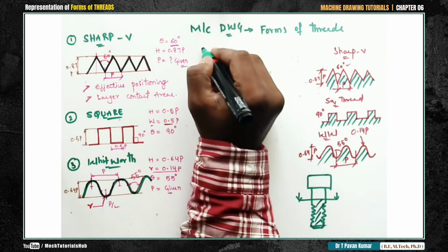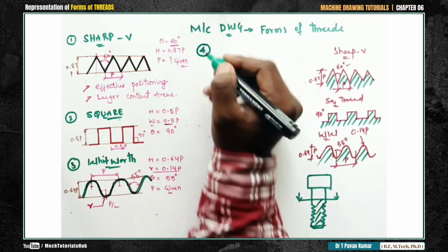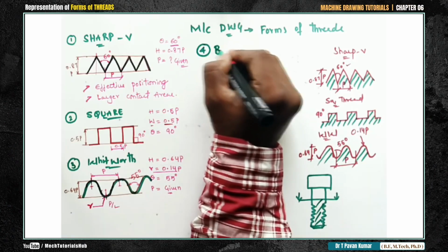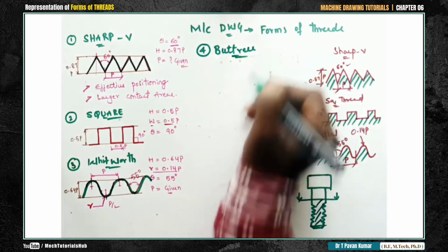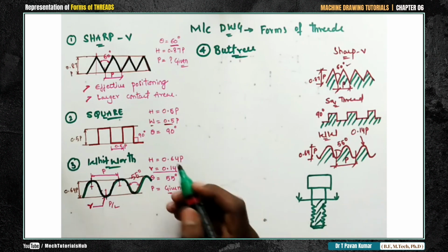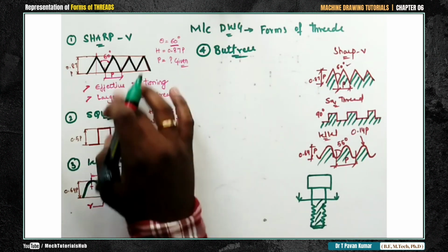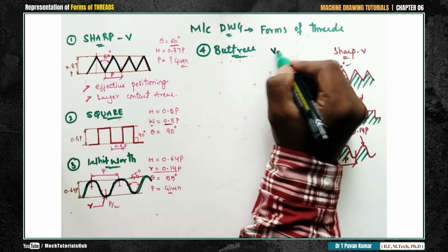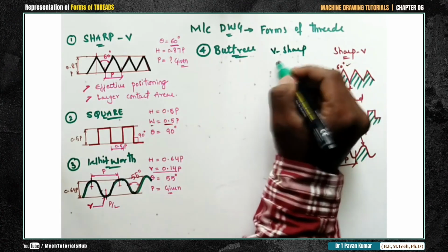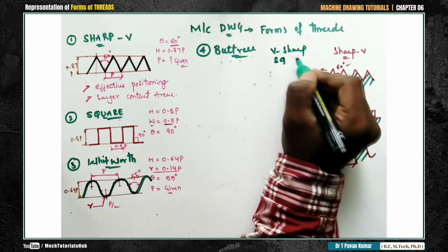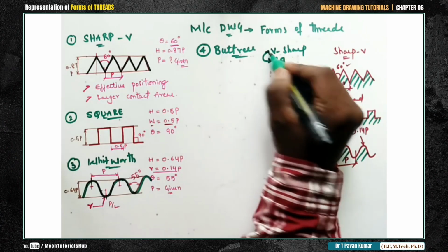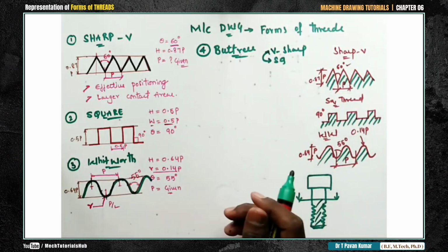Now what you try to do initially, what is the concept? Take value of h, draw one locus, consider that height, draw one more locus parallel to the baseline. Now to place your profile in between, just drop one vertical initially at some distance. The height is 0.6p.